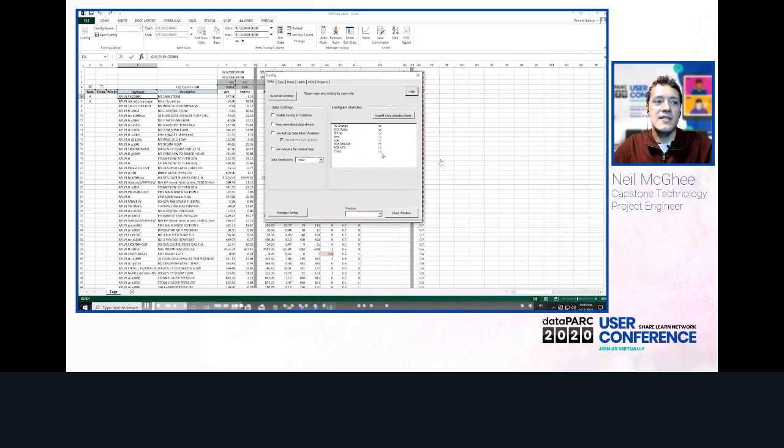The t-test statistic runs a t-test between the baseline period and the comparison period and returns 1 minus the p-value. This is the probability of measuring a difference less than the actual calculated difference if no process change has actually occurred. What this actually tells us is very similar to the SD change, but it takes into account the standard deviation of the comparison period in addition to the baseline. The additional stipulation here is that the comparison period must be long enough that the standard deviation of the hourly averages is also meaningful. I'll go into more detail on the remaining two statistics at the end of the session.